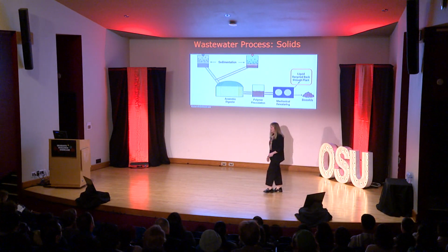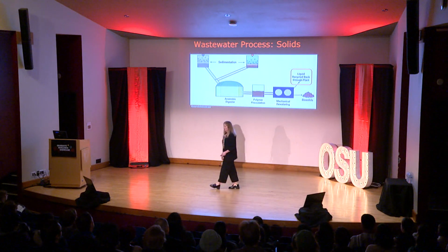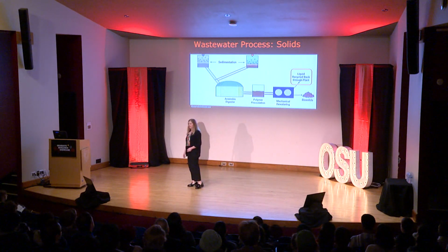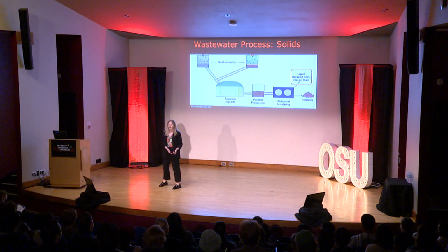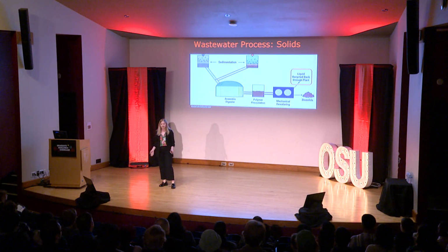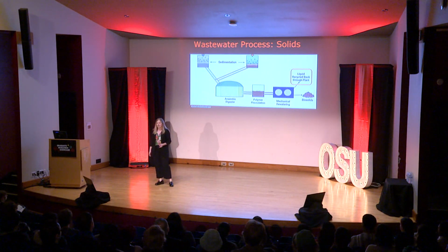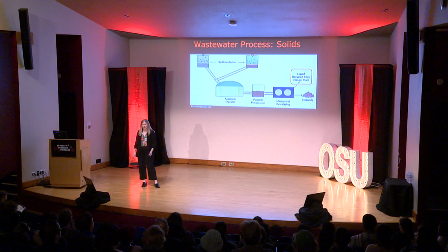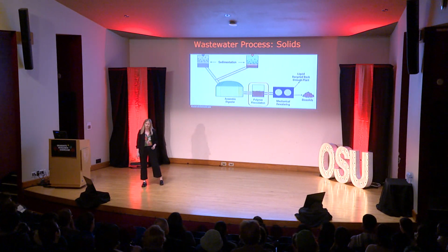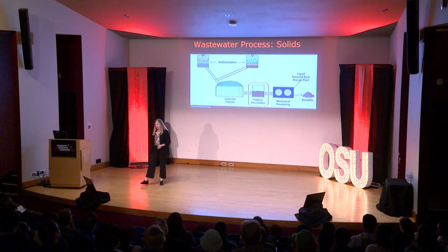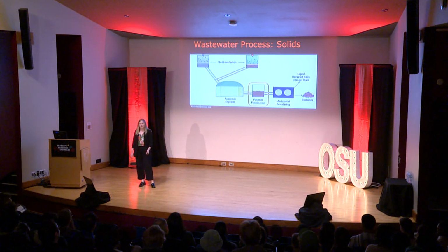The problem is any antibiotic resistance genes still present in that liquid now are going back into the treatment process and mix with all that new sewage that's coming in. In other words, the treatment process itself could contribute to increasing antibiotic resistance within the treatment plant. My research is to try to reduce this. I work back at that polymer flocculation step, researching which polymers and at what dose are better at reducing antibiotic resistance.